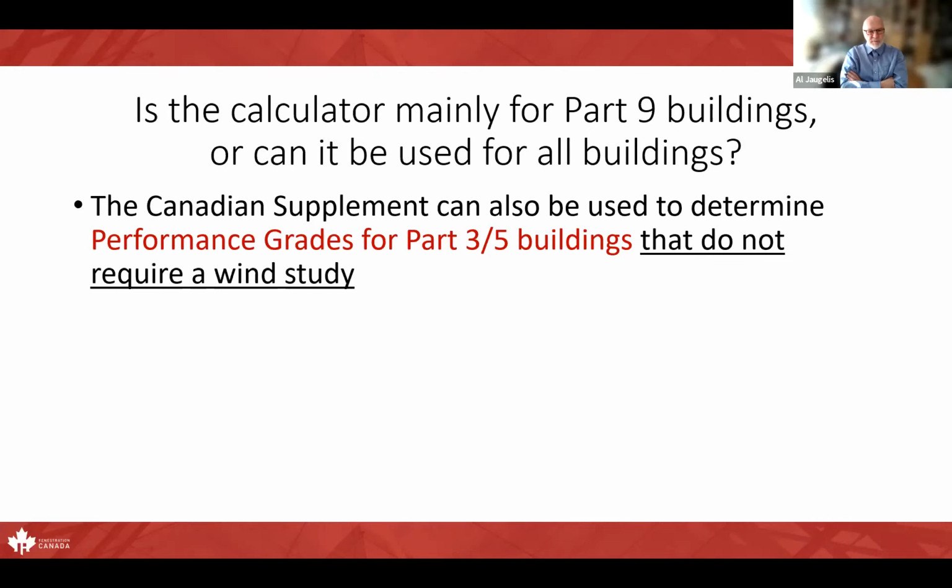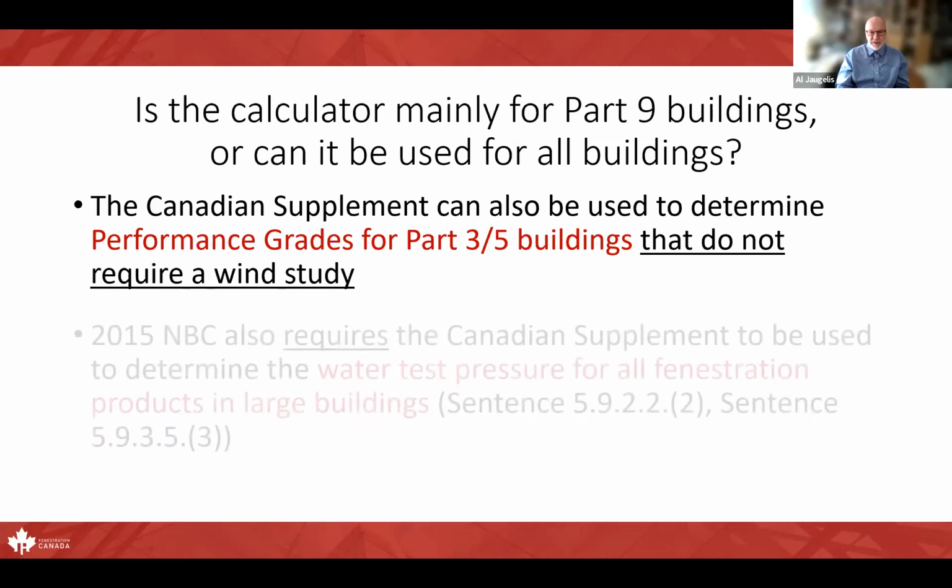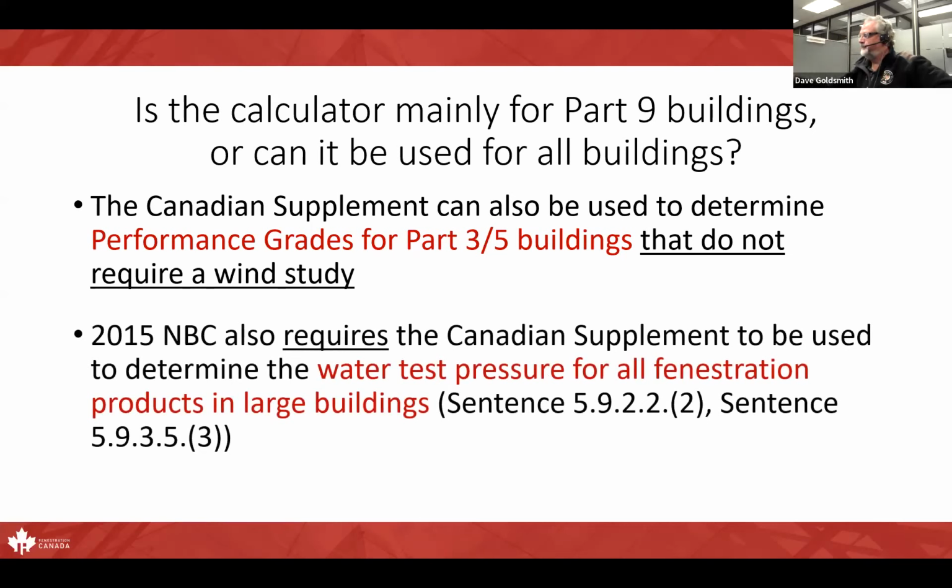That's so interesting. Wow. Yeah, so it's just an indication of how winds can be influenced by the man-made objects that we've put together in various ways. High rises downtown surrounded by other high rises, you do require a wind study for sure. So it's interesting that typically you can rely on the values of the Canadian supplement for the projects you're working on, but you do need to be aware that sometimes that may not be the case. And I think the companies that do the high-rise work are probably more familiar with running into this issue.